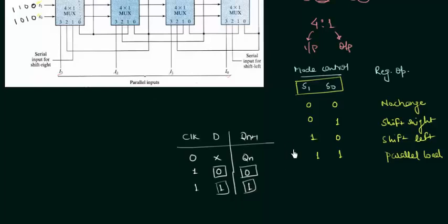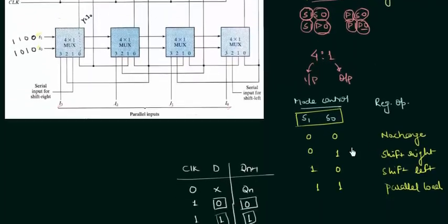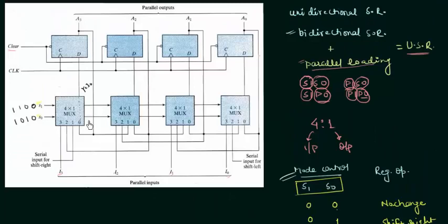So we have everything now to move on and analyze this circuit, and we will prove this table, showing how the selector variables decide our operation. So let's start with the first case when S1 is 0 and S0 is also 0. The input I0 is connected to the output of the multiplexer for all the 4 muxes we are using here, and the output of the mux is connected to the input of the D flip-flop.